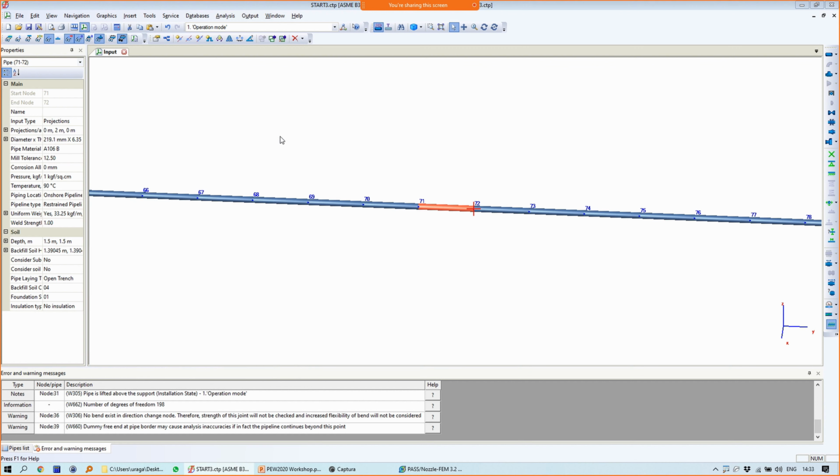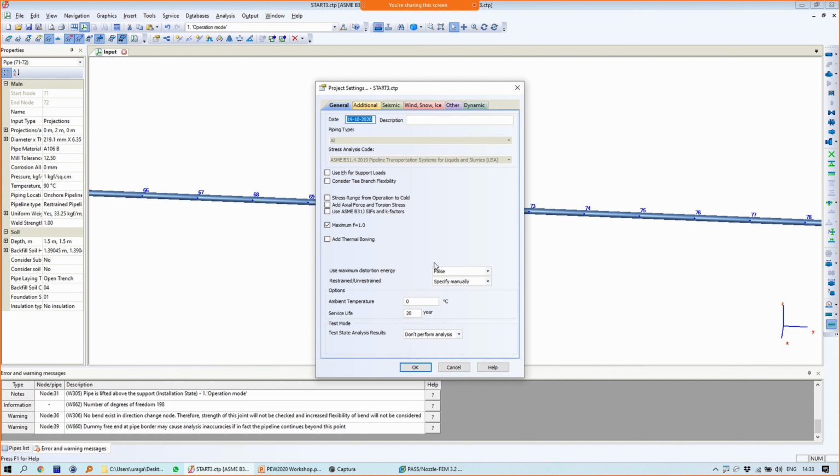We have another feature, auto detect. Starproof automatically checks the axial load, the internal force in the pipe, and if it's almost close to a restrained pipe, it will use the equations for restrained pipe. And if it's lower, Starproof will automatically use the unrestrained pipe equations.